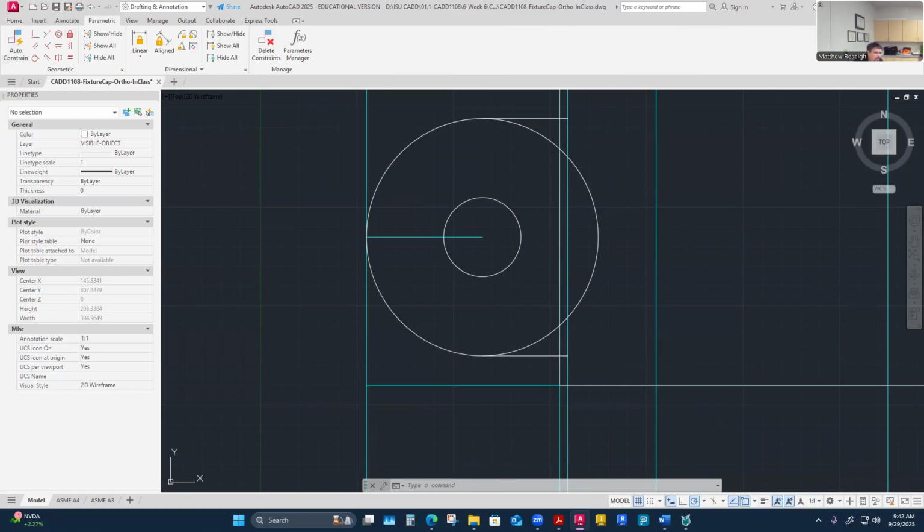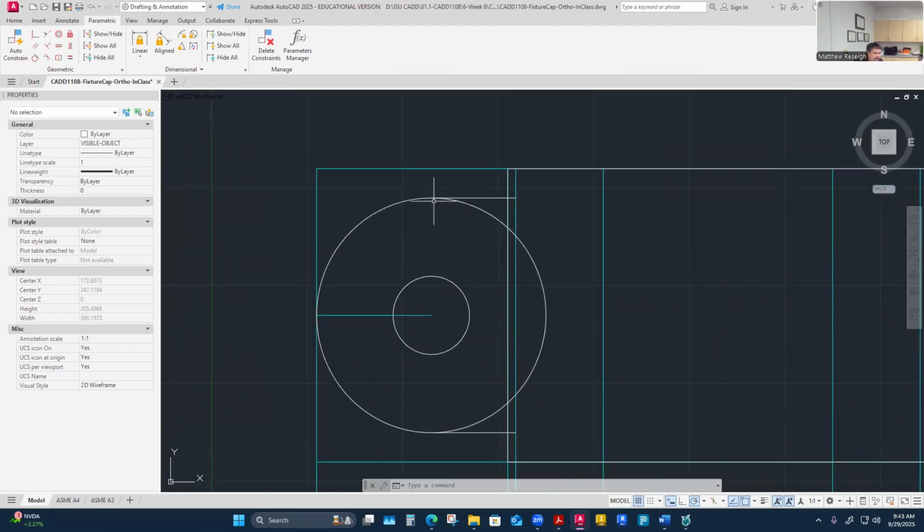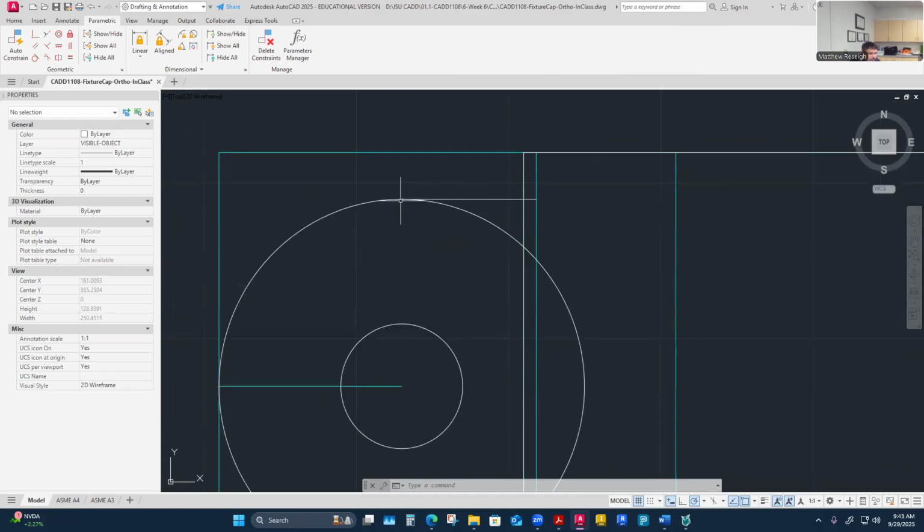But what I'm kind of doing, let me just go off on a little bit of a tangent here. What I'm doing when I picked, hey, it's a tangent that I'm talking about. So it's a tangent on a tangent here. It's like we're going into the Twilight Zone here. Hang on. What I've done is by picking those object snaps, tangent to a perpendicular, I could call those constraints. I'm constraining that geometry that I just drew to remain tangent to that circle and perpendicular to that line.